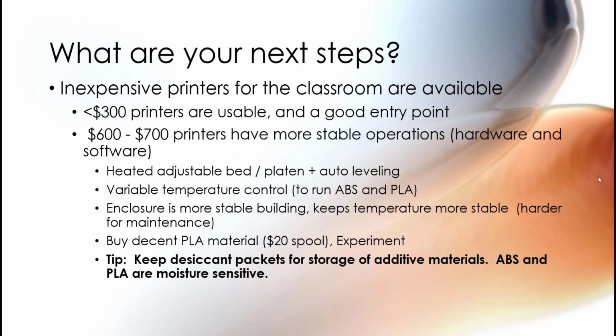Even if your printer doesn't come with an enclosure, something very simple, like a basic box, not a cardboard box, but a plastic acrylic box put over it, will help keep it more stable in terms of temperature. And keeping your bed temperature stable helps the adhesion process.